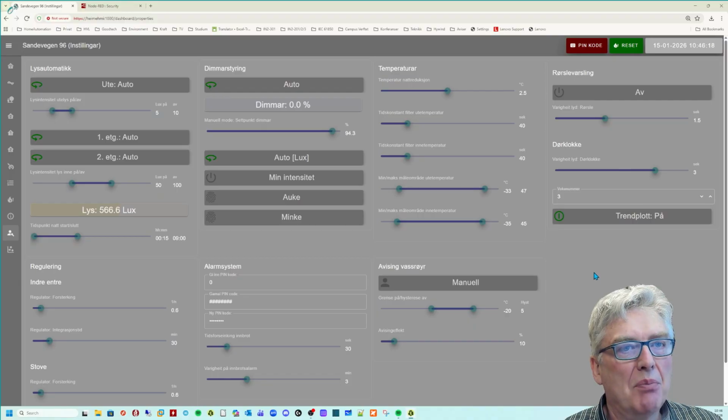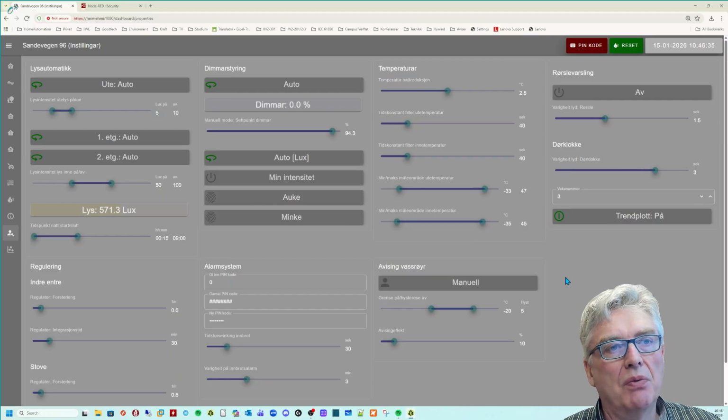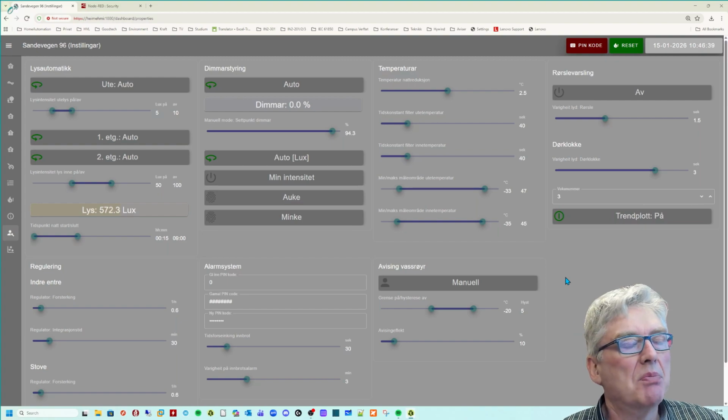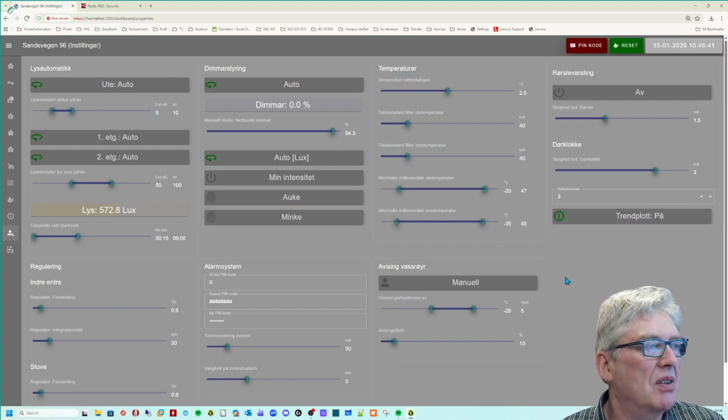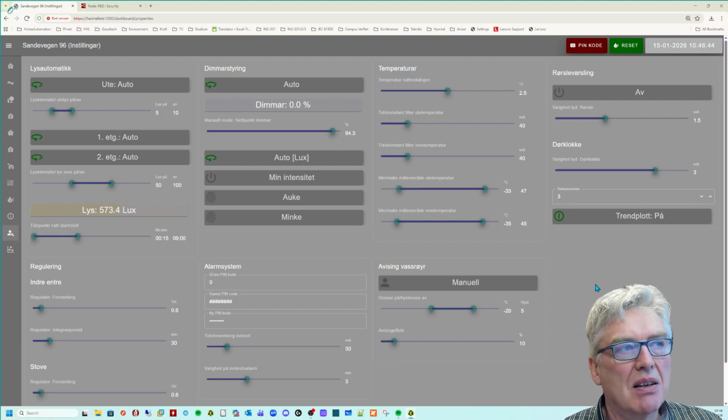But you never put any control whatsoever in your HMI. Nothing. It doesn't do anything. It's just a window into your control, and that's it. Because this one, the Raspberry Pi, isn't all that bad. But say a PLC is made to run for 20 years without an error. And you don't get your PC to do that, or a Raspberry Pi or something. You get an update and everything crashes and things like that. So that's the reason why this is just a window into your real control.